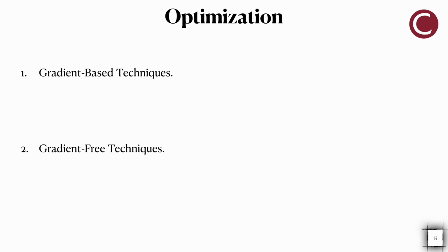So a more reliable and robust alternative for non-smooth objective functions and, in general, nonlinear dynamical systems is the gradient-free technique. And well, the gradient-free algorithms require numerous CFD simulations depending on the number of design variables. In this study, we use the gradient-free mesh adaptive direct search algorithm as our optimization algorithm.